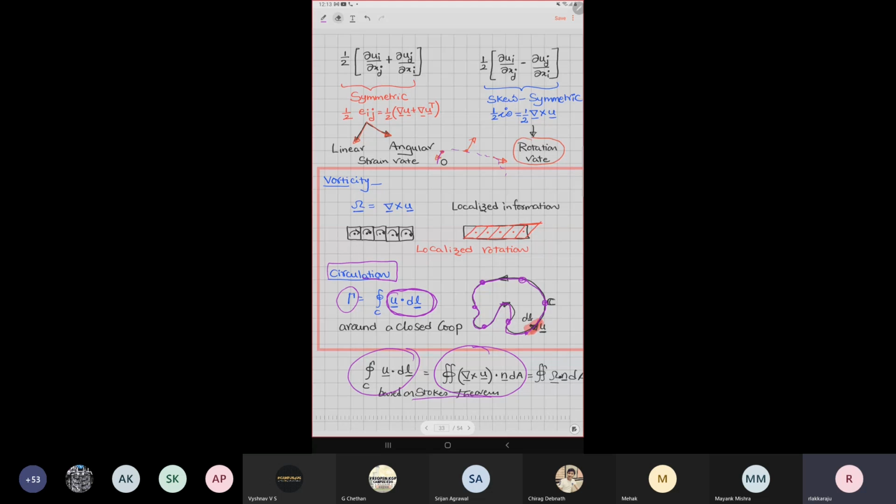Once you know velocity, because I cannot measure vorticity, the curl, everywhere inside the system, what I can do is calculate this circulation around the object as U dot dl at a finite number of points. If I calculate the integral value, that, based on the Stokes theorem, is supposed to give me vorticity. If I know vorticity, I can calculate any other things. I can manipulate anything. That is the way mathematically they tried to define this circulation concept. Is that clear to everyone?